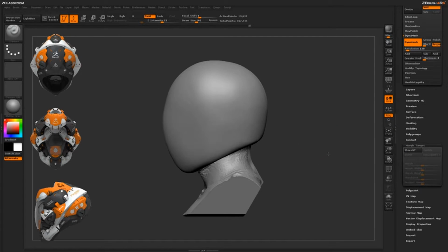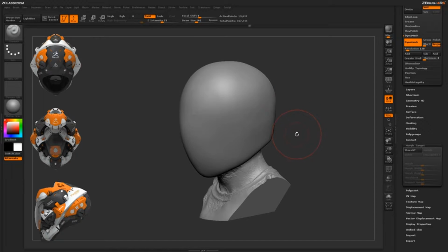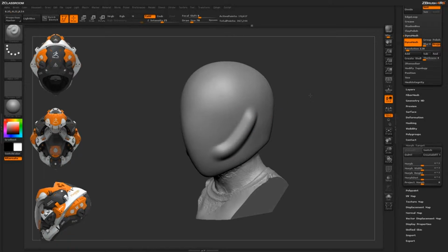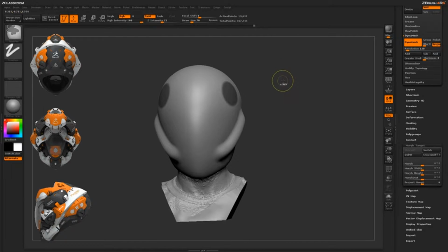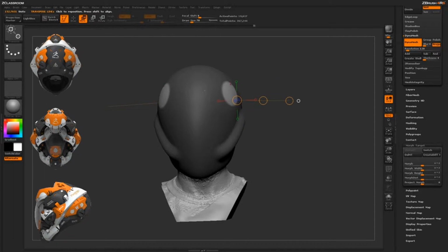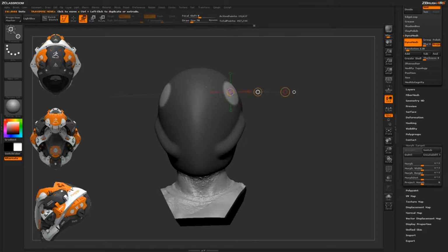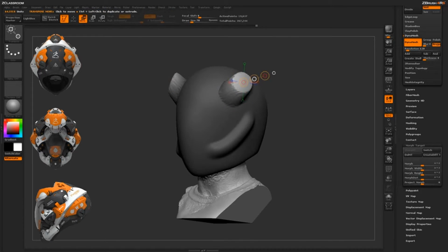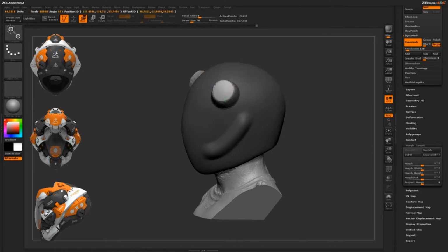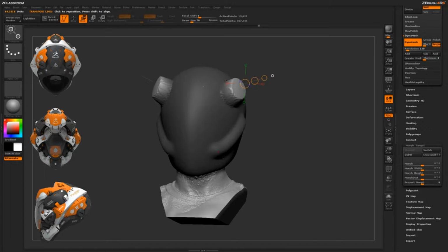on your object. So the main idea behind the Create Difference Mesh is that first you have your object, so we have this helmet interior shape here. We're going to store a morph target on that, and then you're going to come through and just sculpt on your model. You can just do traditional sculpting. You can also do things like masking, inverting it, and then using your transpose lines to deform that surface. So just anything that you can do in ZBrush that involves manipulating the surface of